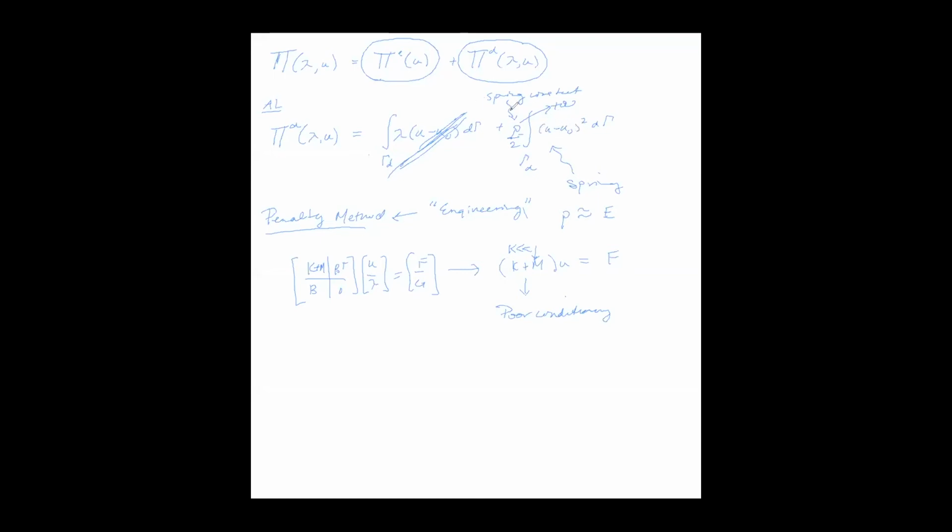In other words, we say the penalty method is not consistent, in the sense that if you were to derive the strong form for the penalty method, there's no natural enforcement; it doesn't match the standard strong form that you would expect, in the sense that u equals u naught. You'd need this penalty to be an infinite value in order for that to happen. So we say that this is not a consistent method. But nevertheless, I would say it is the most popular method because of its simplicity.